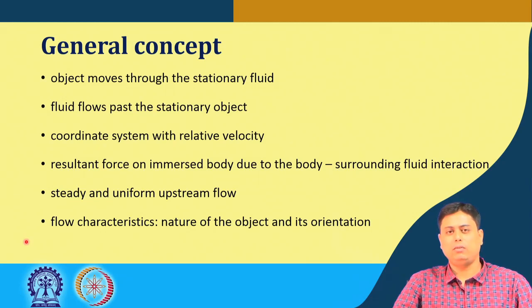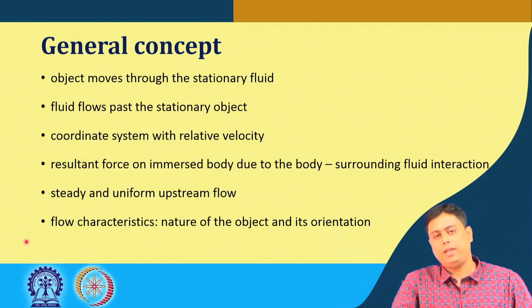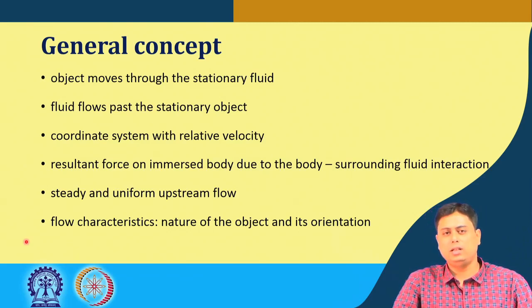Now, here there is a resultant force on an immersed body due to the interaction between the body and the surrounding fluid. In all the cases that we have seen till now, all these understandings are based on one vital assumption: that the upstream flow is steady and uniform. Okay. So, if you remember the flat plate example, there was an upstream velocity of the fluid, where we assumed that the flow is steady and coming onto the plate with a uniform velocity profile.